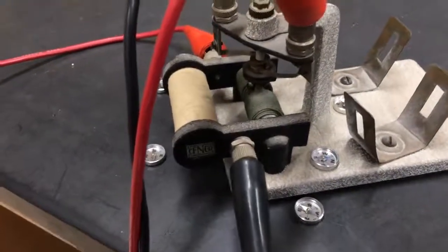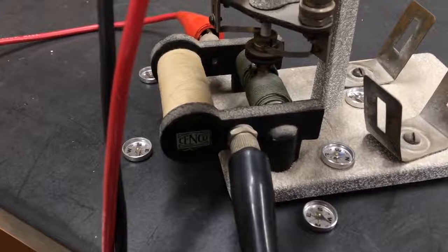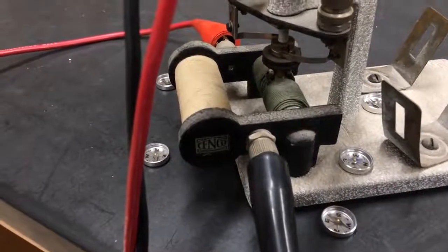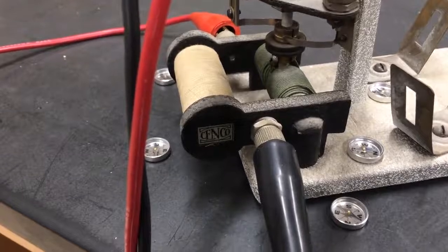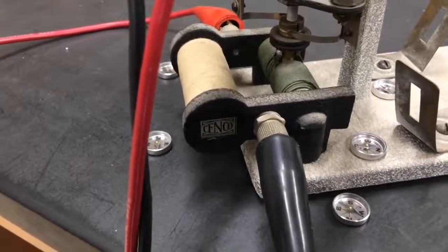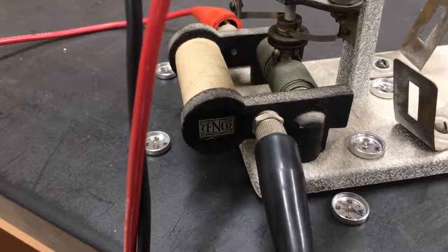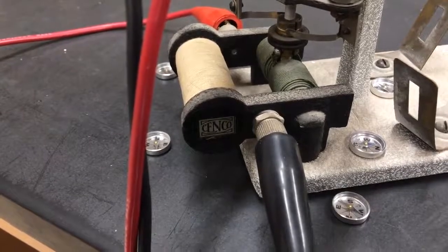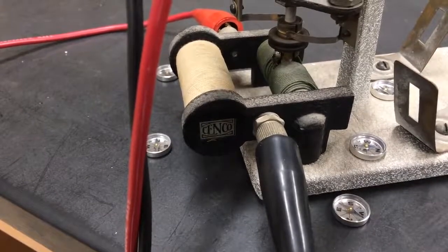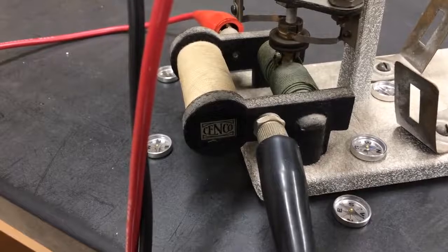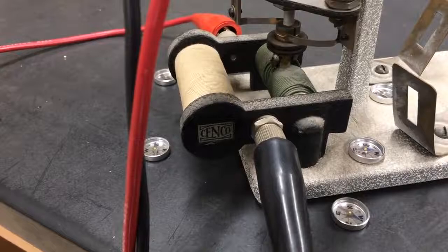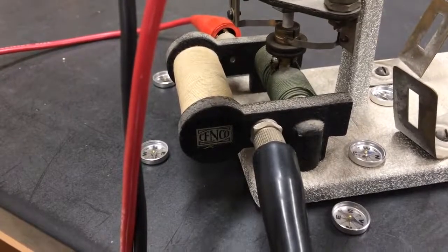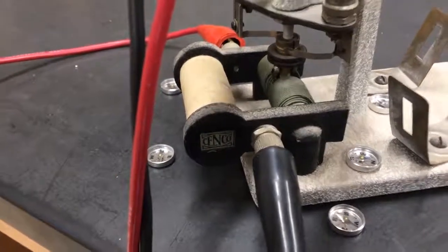So remember, the problem with DC motors is the current never switches direction. So if I was going to do the right-hand rule in this case, for argument's sake, let's say the left side of that green coil, the current is heading upwards. The imaginary positive charges are pointing towards the ceiling. In other words, it's rotating clockwise from our perspective. Let's do the right-hand rule and see what happens.